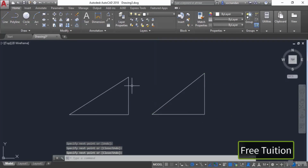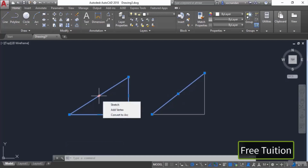So in the first case, when you click on any of the segments, the complete segment will be selected. But in the second case, selecting the segment will only select that segment. Also, we have this additional grip, which is quite different from the grips which we have here on the polyline. And when you hover your cursor over the polyline grips, you'll see this additional menu, and we'll learn about this later on in this course.